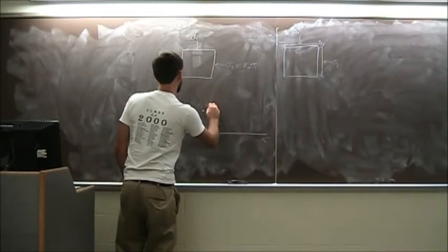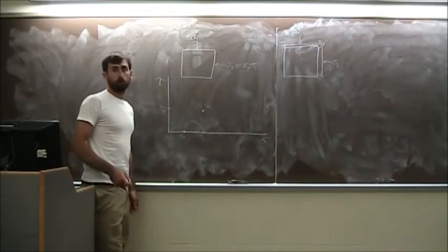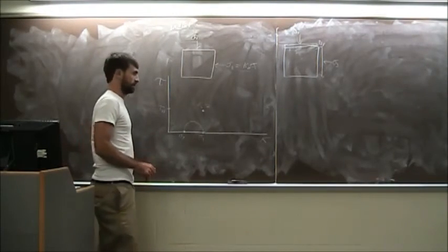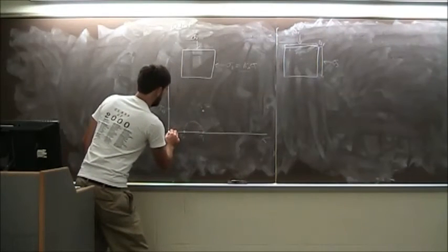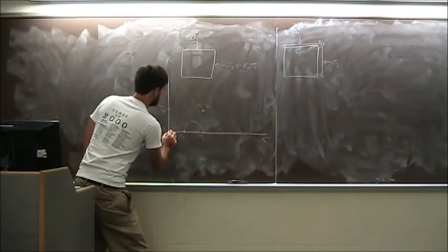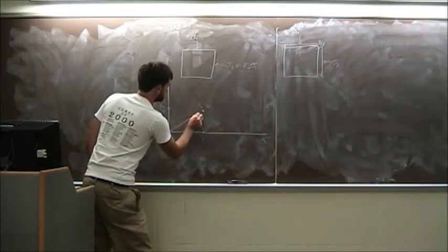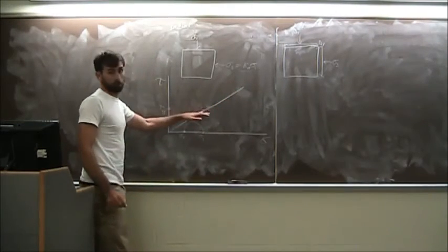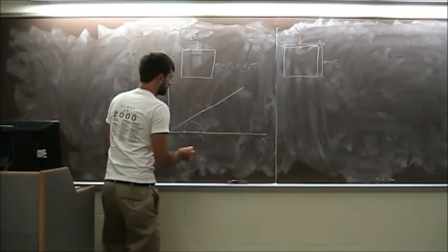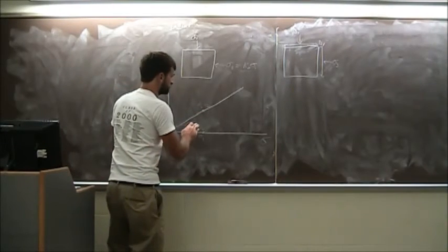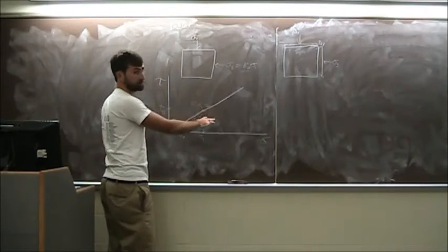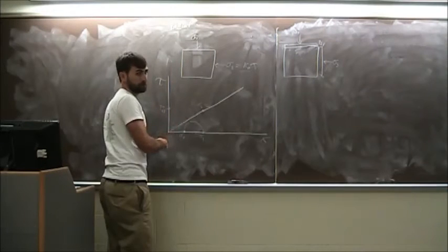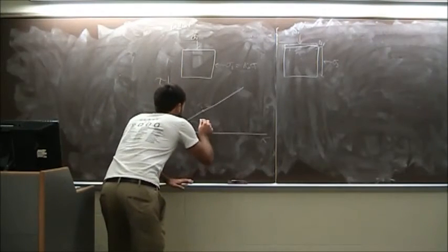Sigma 1 tau FF. Okay. And if we're going to go with a more Coulomb failure theory, we're going to assume it's a granular material for this example. We have the failure envelope goes from 0, because it's cohesionless material, through that point. And that point represents where one of these circles touches the failure envelope, because that's the definition of the failure circle and failure envelope from the Mohr-Coulomb failure theory.